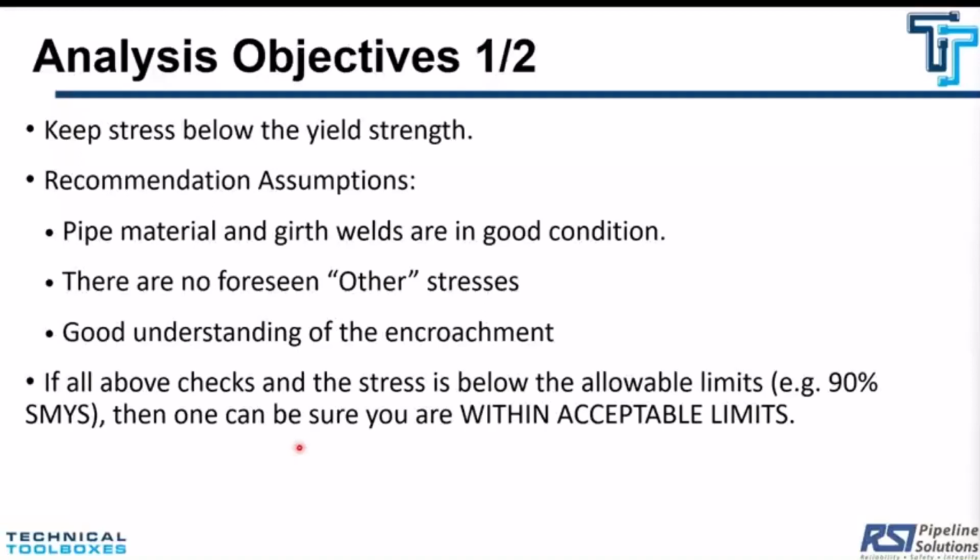Now, the acceptable limit that we use in a typical surface loading analysis is 90% SMYS. By the way, 90% is not the default value in the calculator, but it is the value that the commonly used standards in North America recommend, for example, ASME B31.4 and ASME B31.8.